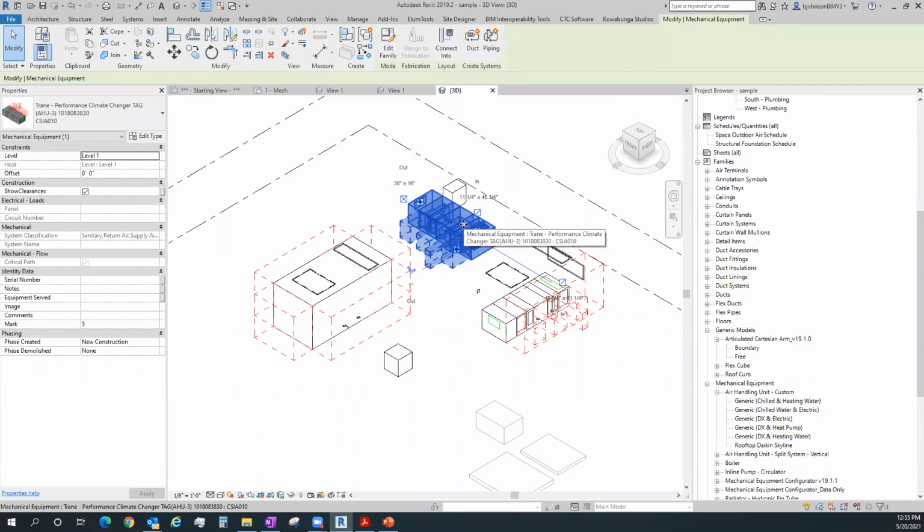And it's kind of like an electrical user placing a disconnect switch on a piece of mechanical equipment and then typing all the load data in on it so it can be circuited inside of Revit. It's almost the exact same idea. It's just another way to say, it's too complicated for me to mess with families all day. Let me make a placeholder that just contains data, and I can schedule that data directly from that object instead of the thing that I brought in that's a monstrous beast that I don't want to change.